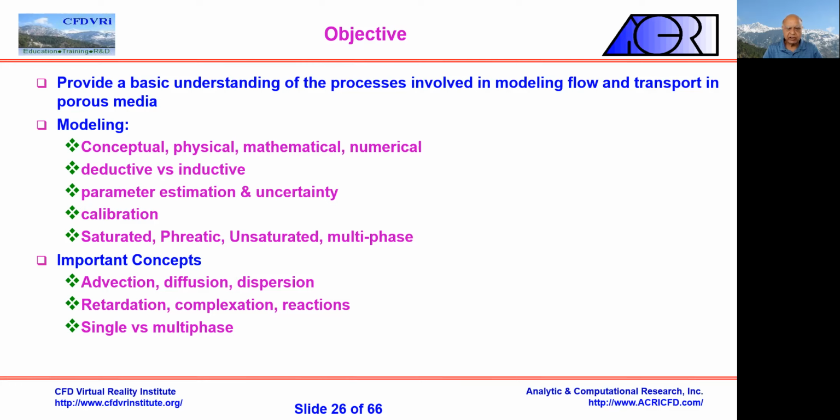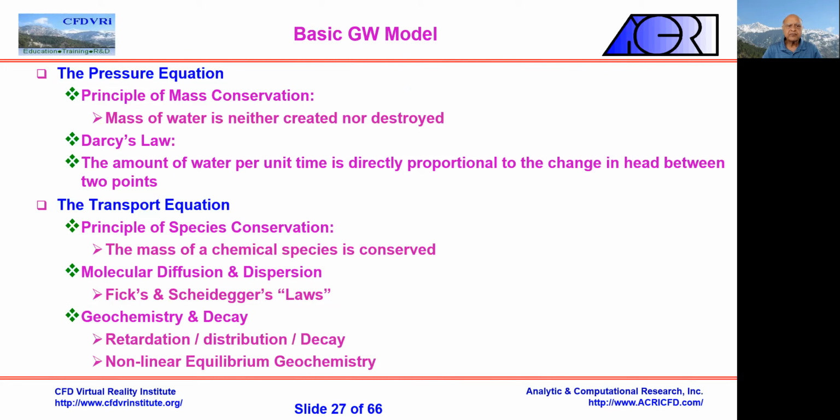And of course, you already know that in these equations, things such as advection, diffusion, dispersion, retardation, complexation play an important role. A basic groundwater model solves the equation on the basis of Darcy's law. The principle of mass conservation is there, continuity is there, but basically the momentum comes from Darcy's law. We'll look at it in a minute.